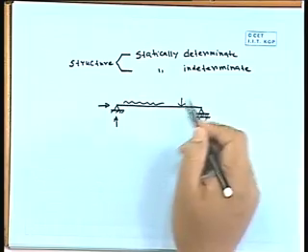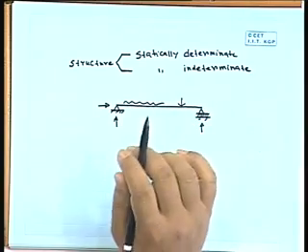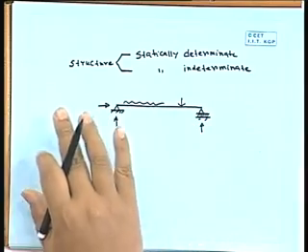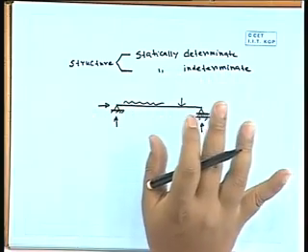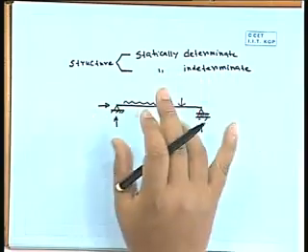So for any unknown or undesirable horizontal force, we have to prevent that, at least at the left end or right end. It may be 0 or any small value depending on the type of load. Theoretically, for a beam problem, usually we are not going to take any horizontal load, so it will be 0. So that horizontal force condition is automatically satisfied. From the 3 equations, normally one equation is automatically satisfied, so the other 2 equations are there. From there we can find the 2 reactions.